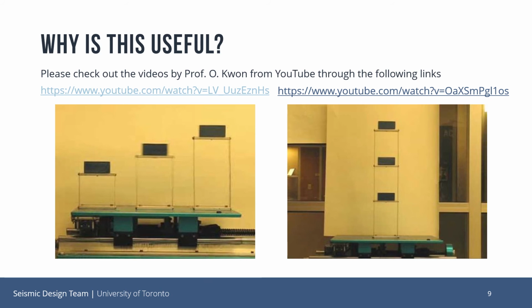So this is the fundamental mode shape. Usually the lowest frequency one is always going to be the most dominant one. Yeah, so that just happened at 4.35 hertz, and then it passed, and now we're going to get to the next mode shape. As these mode shapes become higher and higher frequencies, just to recap the first lecture, their shapes are going to get more and more complicated in terms of how many nodes you have, which is places where there's very little rotation, and how many peaks you have.